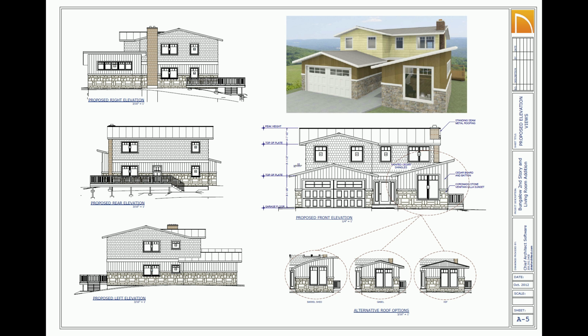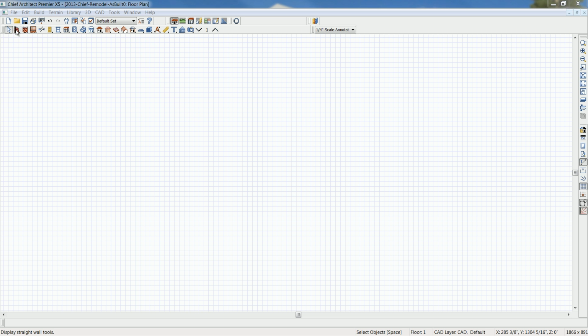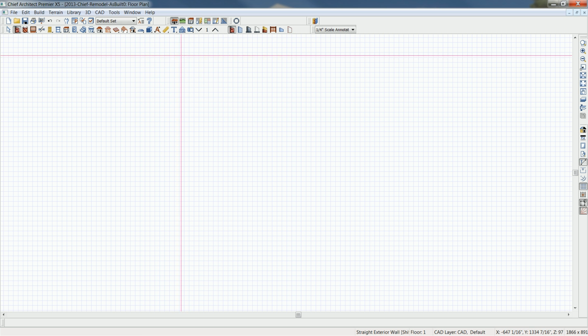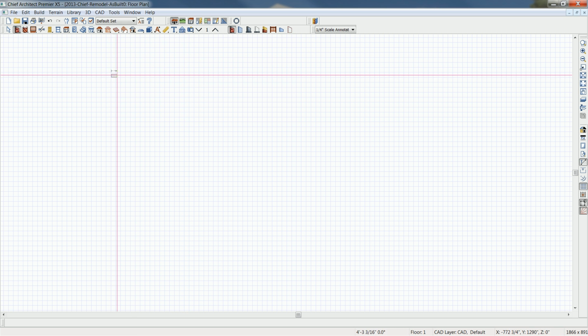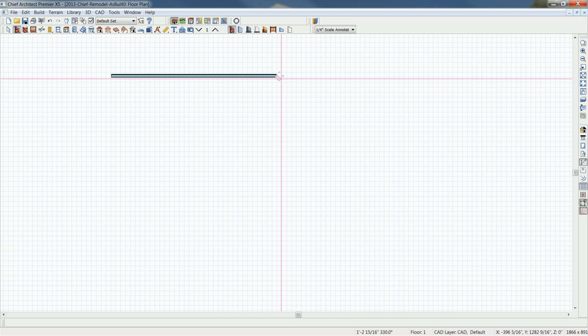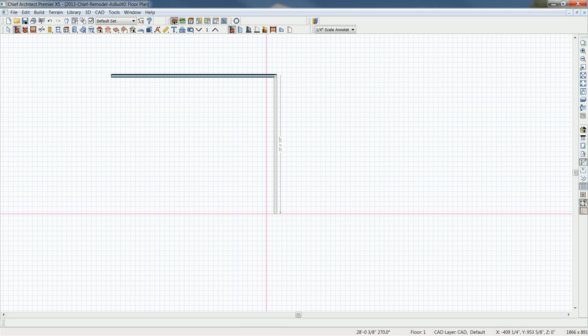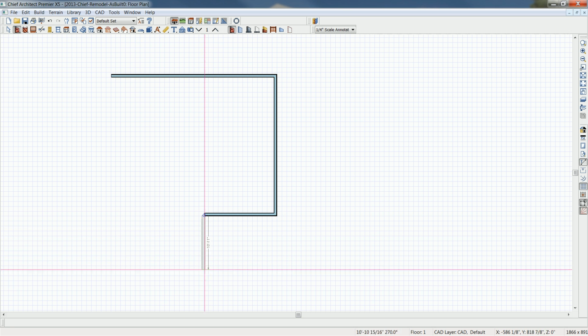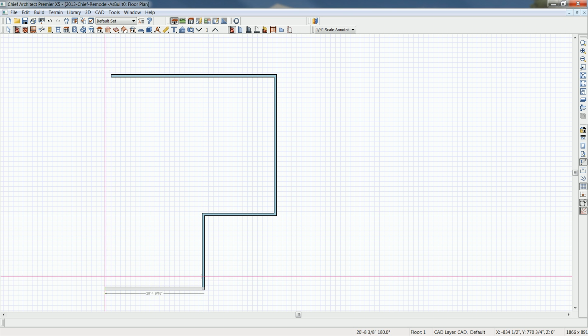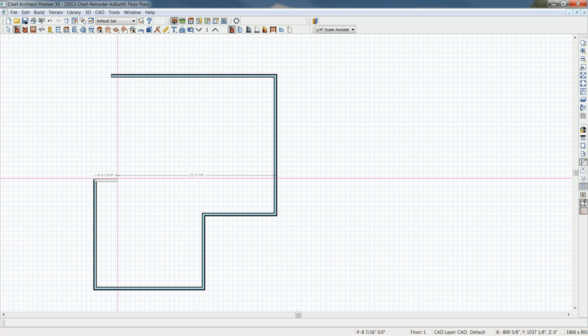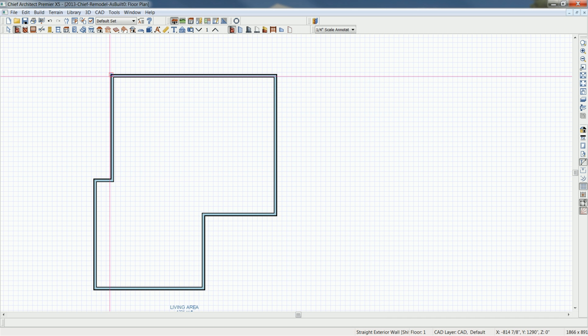I'm going to open up Chief Architect. I'm using Chief Architect Premier. We also have a light version and an interiors version, depending on what sort of work you do. To create our as-built, which will eventually become the basis for the remodel, I'm going to use an exterior wall tool, and I'm just going to come in here and create the shape of the design. I'm not worried too much about the dimensions at this point. Line that up and snap it into place.